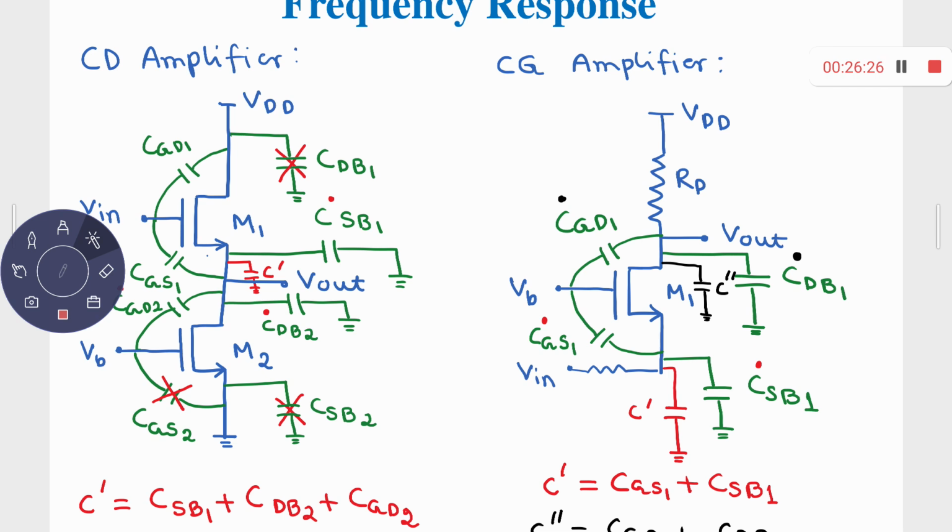Right? Once again, how many signal nodes can you consider? You can consider 2 signal nodes. One is obviously this one, this G1, and second one is obviously your S1 or D2. Same thing, because D2 and S1 are connected. And at terminal D2 or S1, you have different capacitors which are connected in parallel.